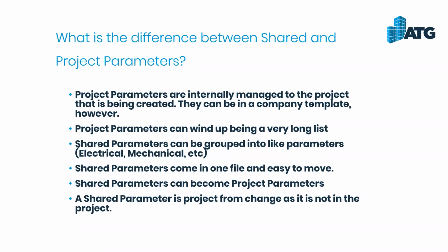Typically, you don't want to move a shared parameter around from one location to another because users are going to point to that one location within a company. But if you are maybe sharing shared parameters with a consultant so that they have the same shared parameters that you're using, that is an option.